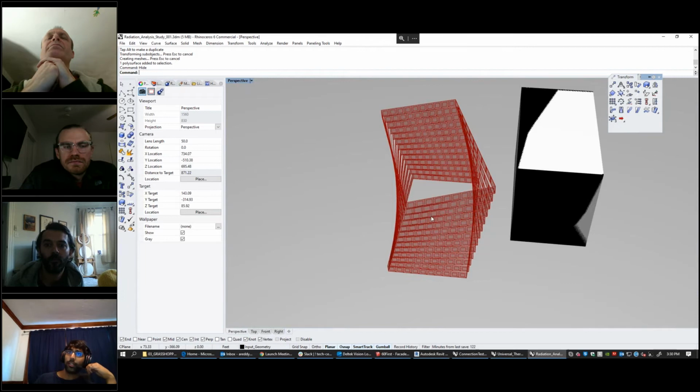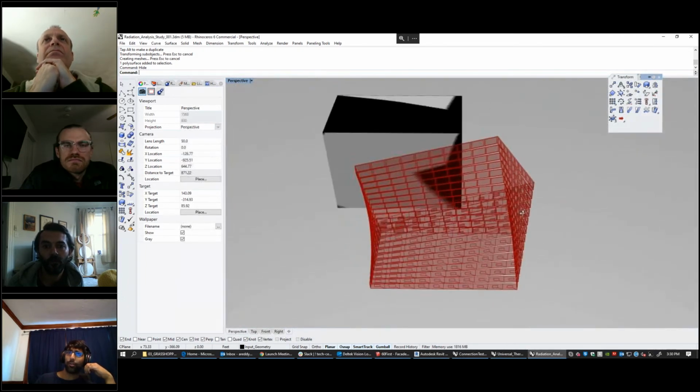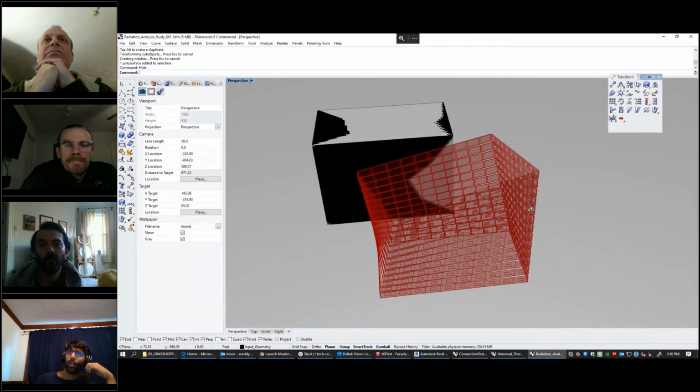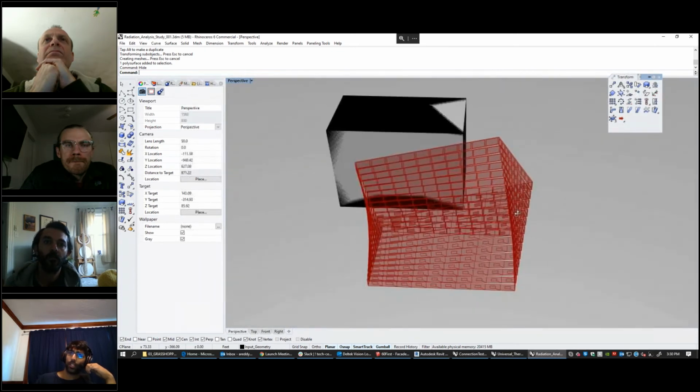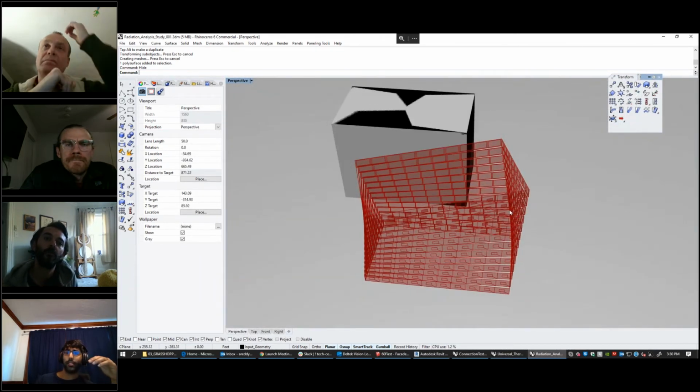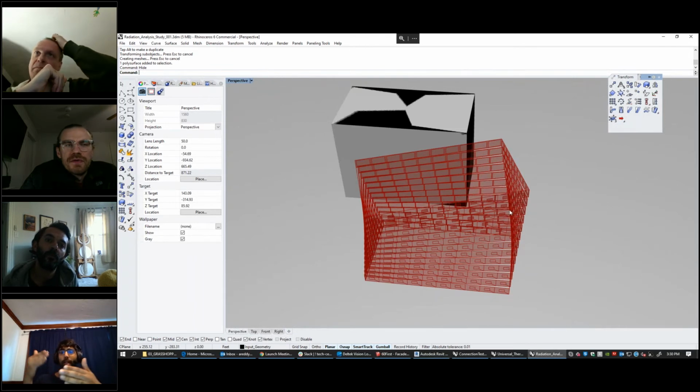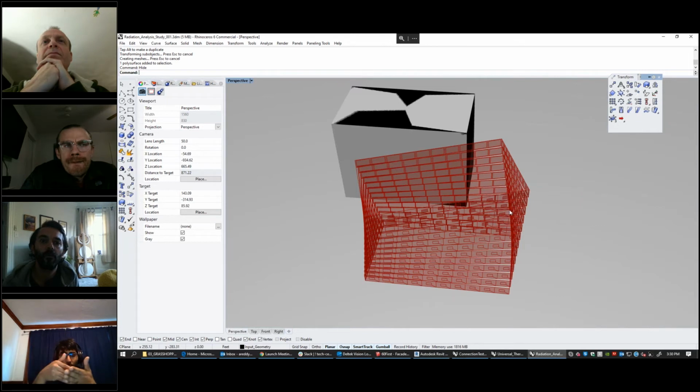And I was making this out of flat faces because Ladybug can't do curved surfaces with this radiation analysis. It really depends on straight lines that come into these flat planes and hit them, and when it's looking for a normal, right? A plane has a normal, but when it's a bent curved surface, it throws everything off and you'll get really inaccurate results. So whatever the analysis geometry, you always have to put flat, fractalized surfaces in. That's why even when I twisted it, I wanted to use flat faces.